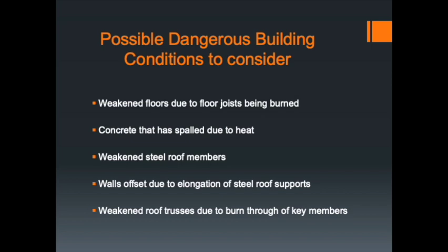So here are some dangers to think about during the overhaul or during the fireground operations. Just think that the building's been burning for a while. So the walls, the floors, the actual integrity of the building has been compromised to a point, so be cautious. Roof members are heated, especially if they're steel. They're going to elongate, and that's going to cause walls to push or for mortar to loosen.